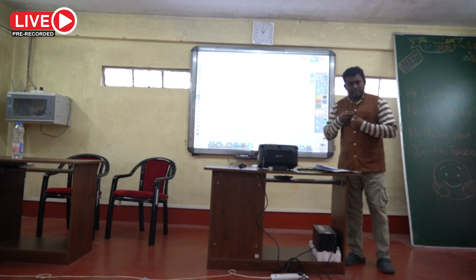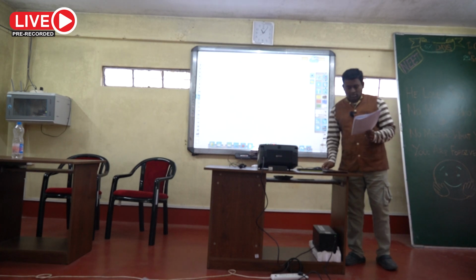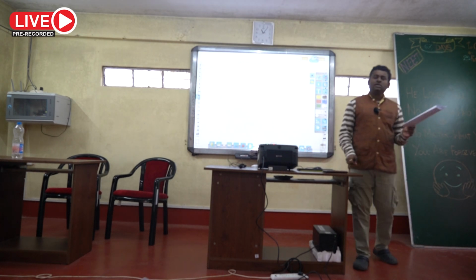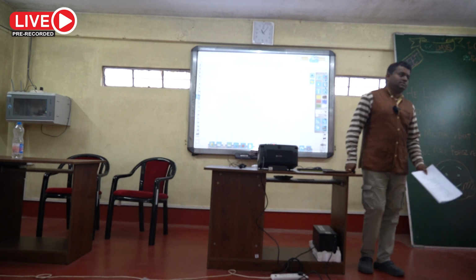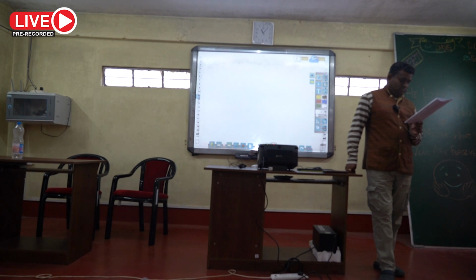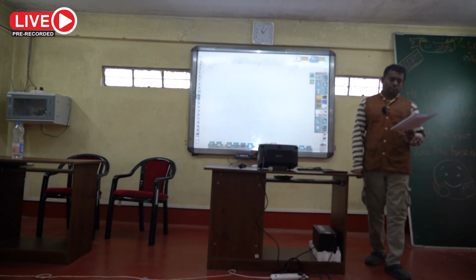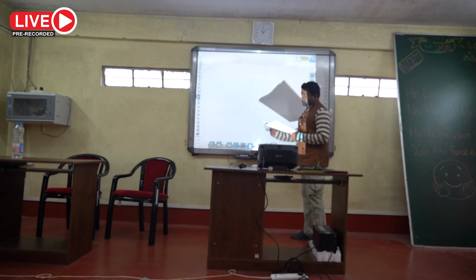That is 2:5. So it is a balanced Wheatstone bridge. So no current will flow through the 12 ohm resistor. Then what is the current flowing through the 4 ohm resistor, that you have to calculate. In the upper branch, what will be the current going?